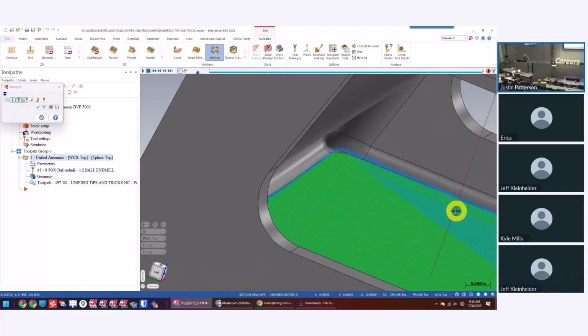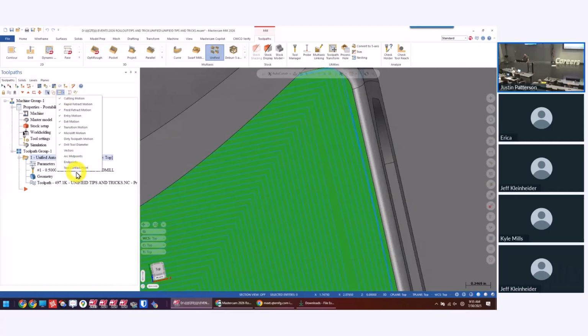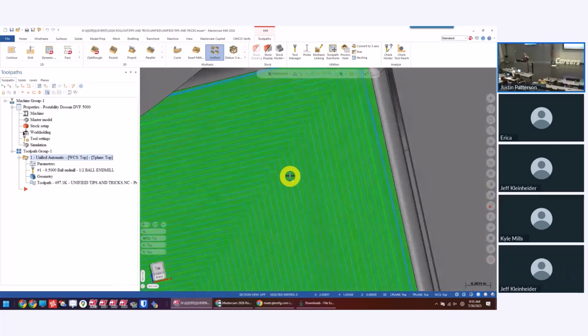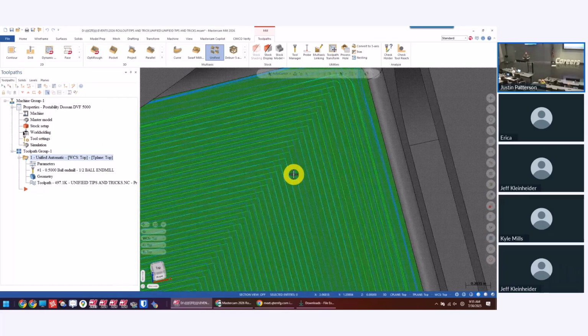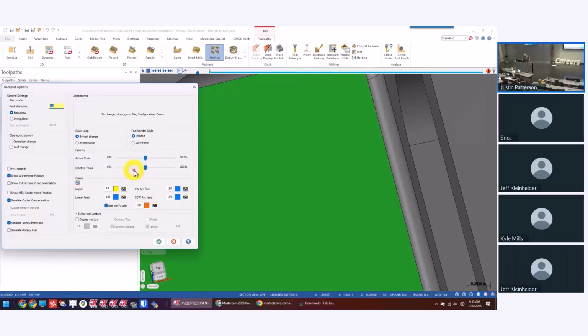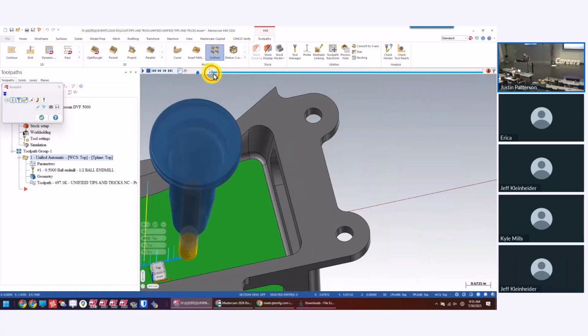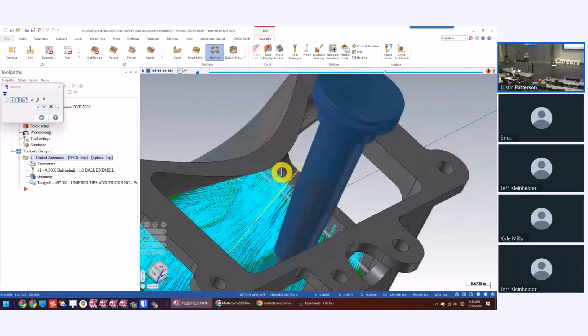But to go back to this, what's it actually look like? Well, underneath advanced toolpath display, there's tool contact point. This came out a while back. If you look at that, it actually projects onto your surface where the contact point of the tool is. This only applies on all 5 axes or just unified, I can't remember. All 5-axis toolpaths. Yeah, anything that has vector data. And if you don't know what Kyle's talking about, if you go into your backplot, go into your exclamation point, here's your vectors. You can display all your tool vectors. Like when it runs, you can display it outside of backplot, but you can see where all our vector changes are happening.